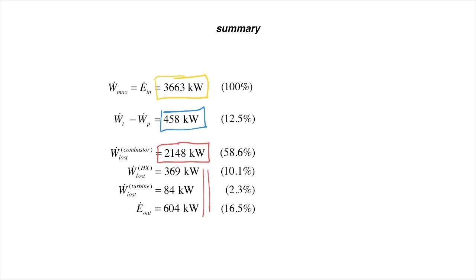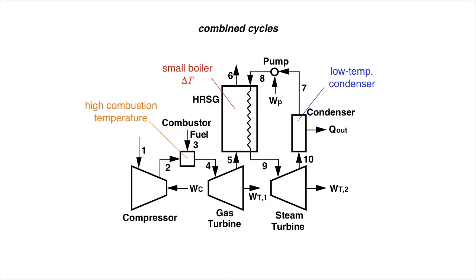So if we really want to improve things, finding a way to mitigate entropy generation associated with unrestrained combustion should feature very heavily in our priorities. One way workers have sought to address the efficiencies described here is using something called a gas turbine combined cycle. Rather than just combust fuel to make hot gases and then boil water at a low temperature with it, a gas turbine engine pressurizes air to high pressures and temperatures where combustion results in much less entropy generation.